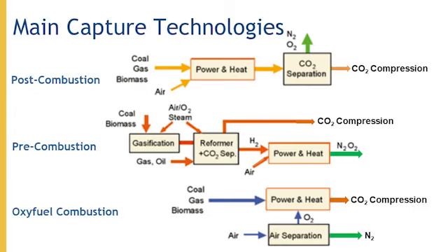Now, pre-combustion is another type of capture technology. It has a few steps prior to that power production step. You can apply gasification and reformation, where you can partially oxidize your fuel to produce a higher volume of CO2. And then your hydrogen-rich fuel can then be burned to produce power or heat.